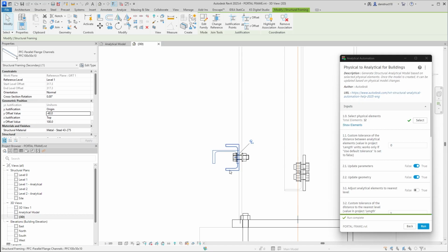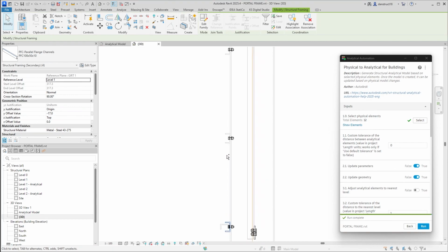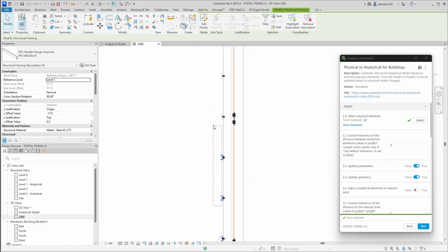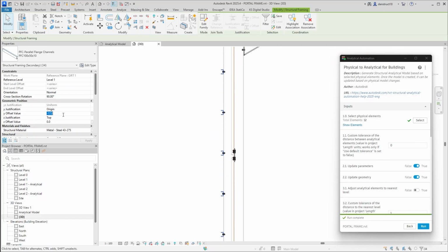So I'm going to do the same thing as well for the other side rails. So I'll make a selection of them like that. Hold down the Control key and make sure that I can select all of them. So hold down the Control key, make a selection, then hold down the Control key, make a selection over those. Change this to -40. There we go. And I will change this Z offset here to 100.